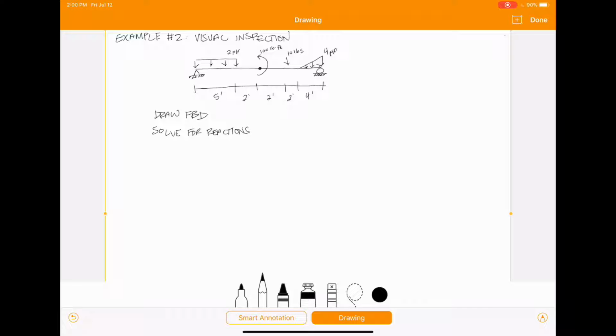So the free body diagram, in this case, you start by drawing your object, apply your external forces, apply your reactions, we'll label all these different points, A, B, C, D, E, F. So this is going to be AY, AX, and FY. So there's your free body diagram.